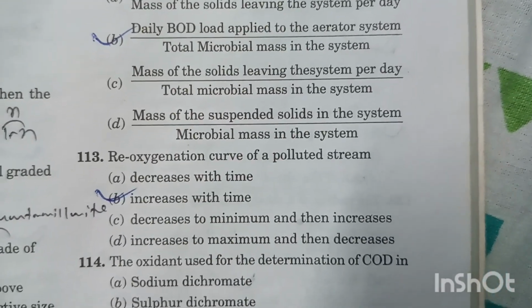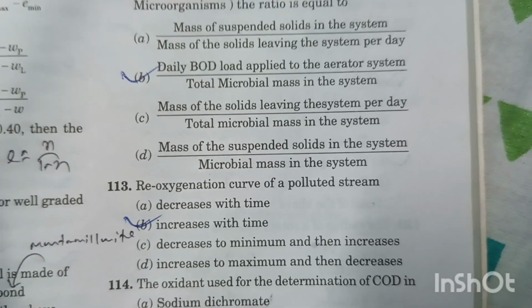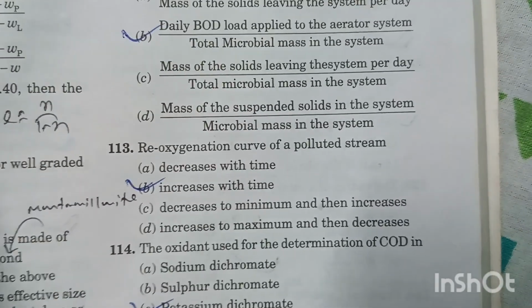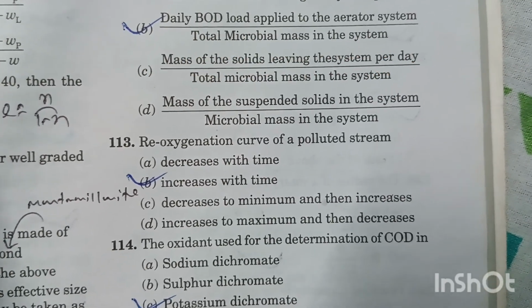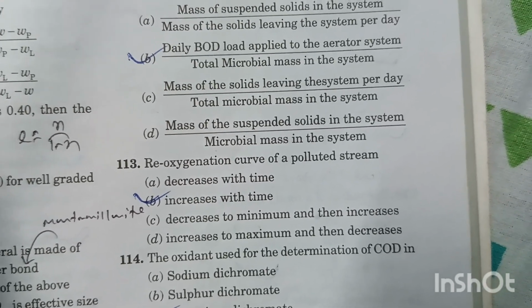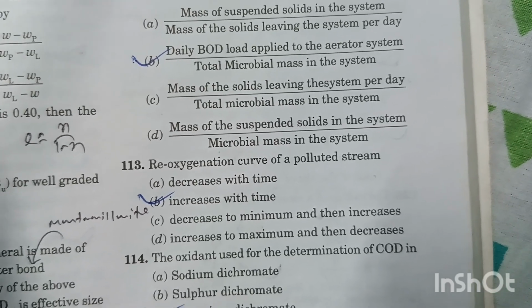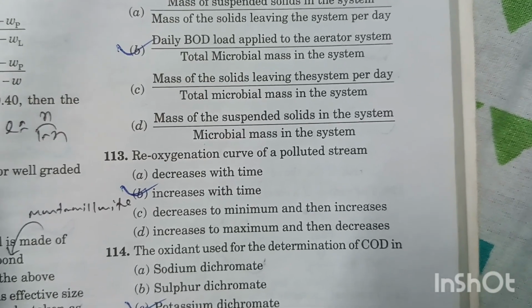Question number 113, the reoxygenation curve of a polluted stream increases with time. Option B is the right answer. To counterbalance the consumption of dissolved oxygen due to deoxygenation, the atmosphere supplies oxygen to water, which is known as reoxygenation, and it increases with the time of flow from the point of pollution. Option B is the right answer.